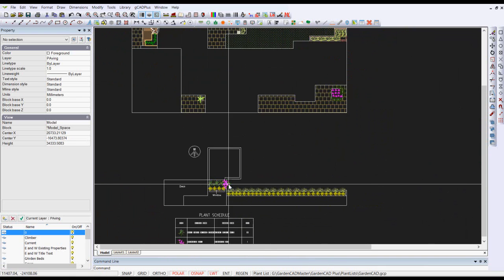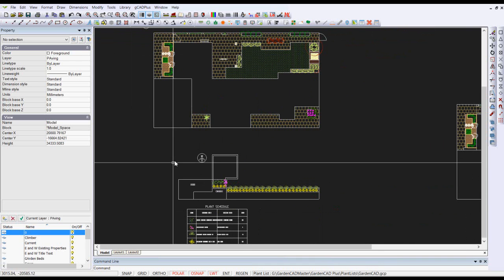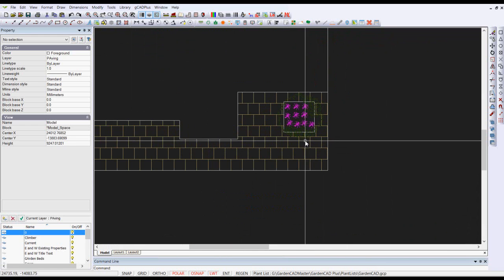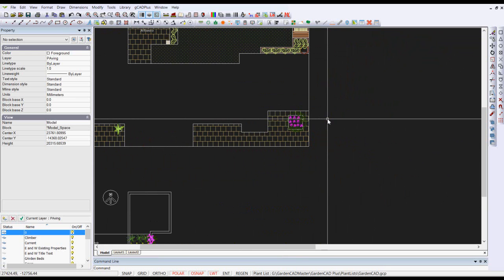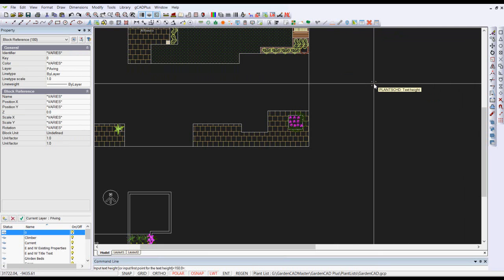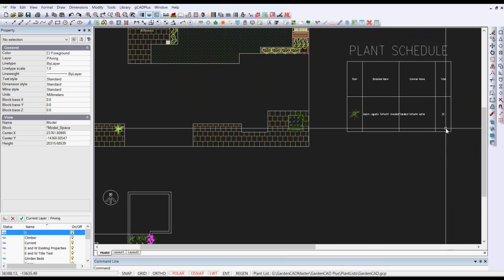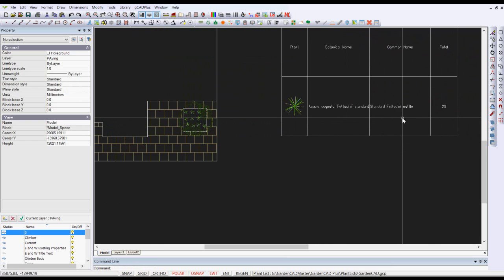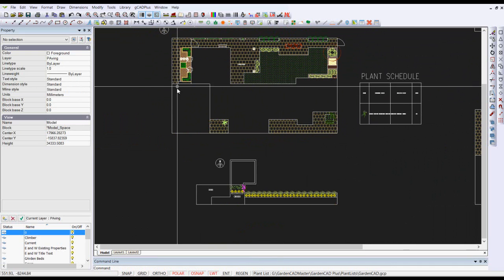The bougainvillea has been drawn with magenta, which was confusing me. So if we run the schedule now, we should get 1, 2, 3, 4, and 6. We should get 10 in the schedule. There should only be one plant in it. So let's try it, and we'll go back here and we'll draw the plant schedule. So repeat that, and 150 for the height, corner point there, and come there. We only get one in, and we get 20 in the list. So that would seem to me, maybe there are others in the design here.